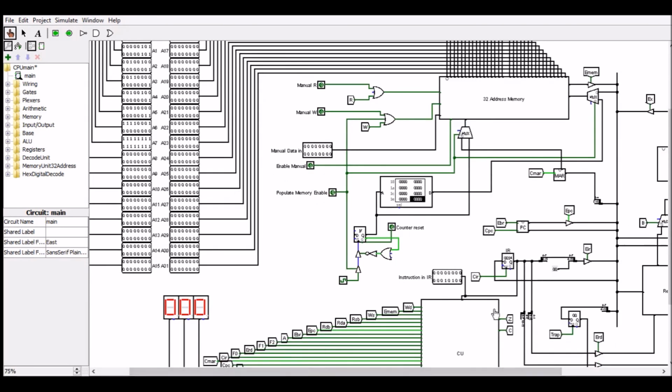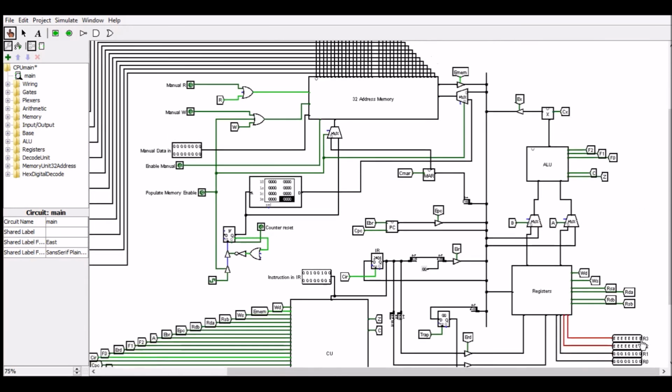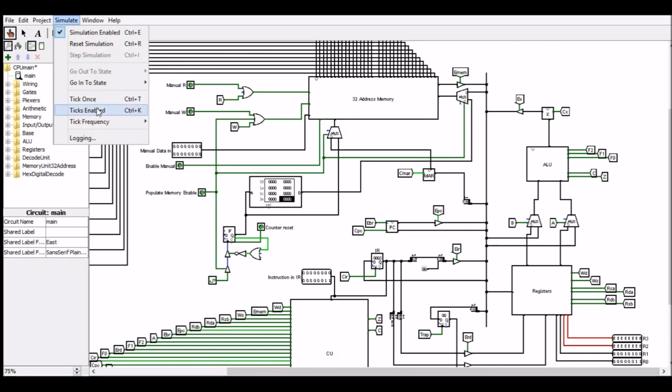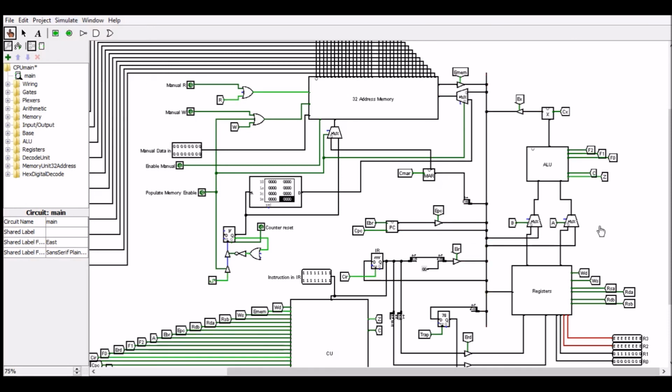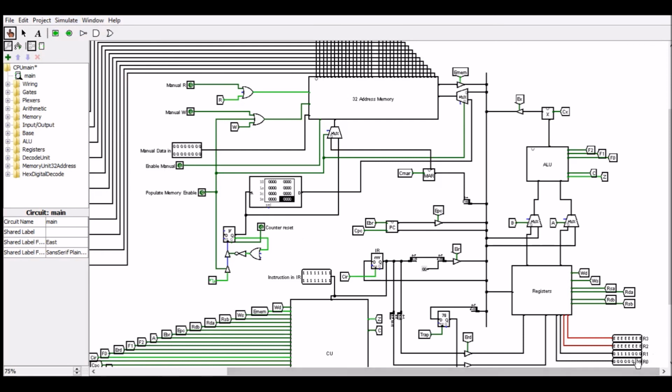So we should see here, if we clock the branch instruction in, we can see that it's been met. And we've gone back to an instruction here, and it should subtract 1 from R0, as we can see. So if I let that run, we should eventually get to R0 being 0, which we have.